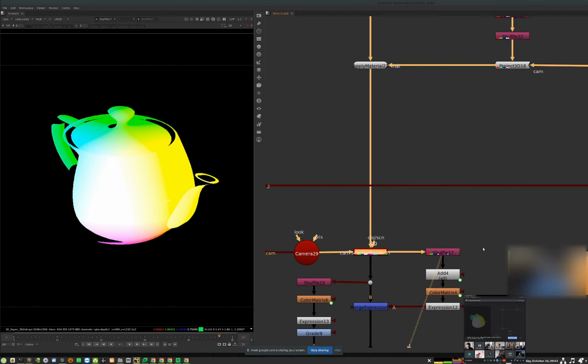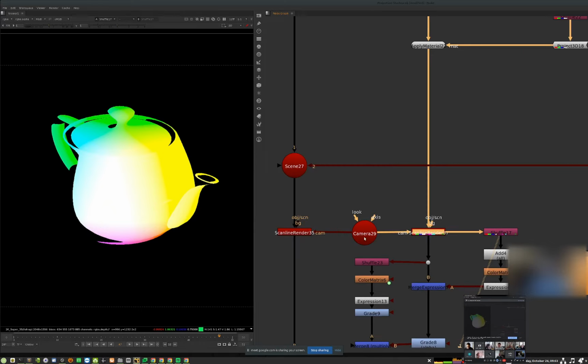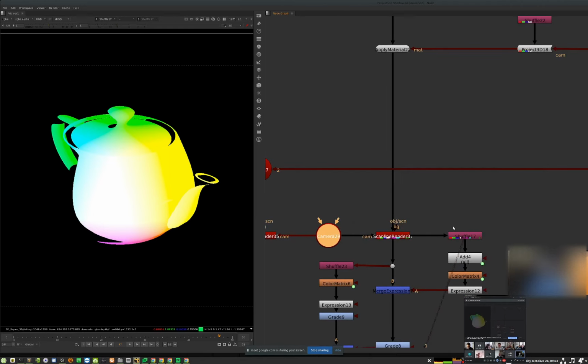And depth is not a distance equation in a rasterizer or in most renderers. I think it's a bit confusing to some. It's actually the Z component of the P-world. And it's not the same thing. This thing is kind of like spherical distance from things, and Z components will be a planar thing. And they're not the same values. They could be very close, but they're not the same values. So this is important for us. When we are rendering, we actually render the depth, which gets the Z component, which means if we can actually get the P-world Z component somehow, we will get the right depth, which is what we're trying to do over here.